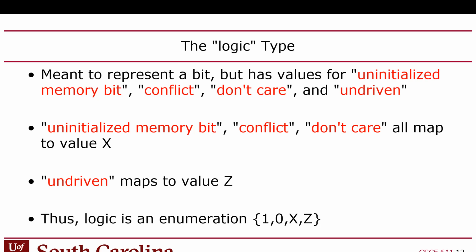Likewise, there's also a special value for when two or more logic gates have their outputs connected to the same wire, shorted together. If two logic gates are both driving, in other words trying to set a value on the same wire, they can be in conflict if one is trying to put a 0 on that wire and the other is trying to put a 1.